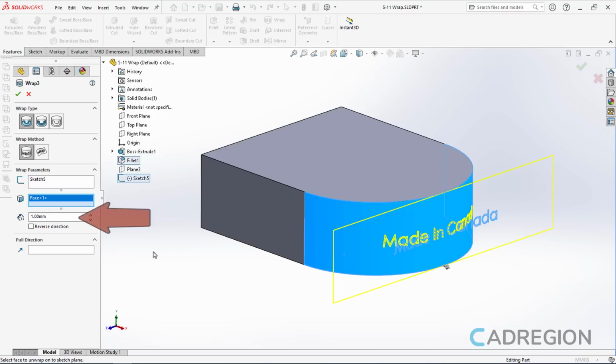Now we'll go to the Thickness field and I will set the thickness of the feature. However, before I do that, I have to select if the text will be embossed on the object or carved. So I will go at the top of the Property Manager palette to show you the available wrap types.